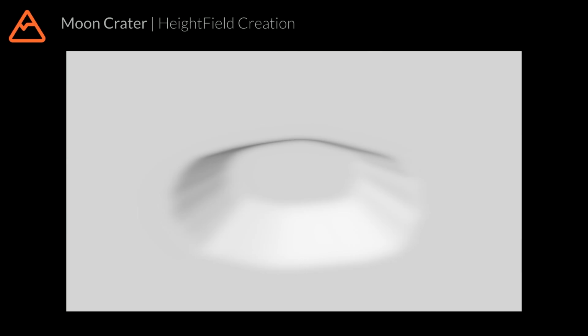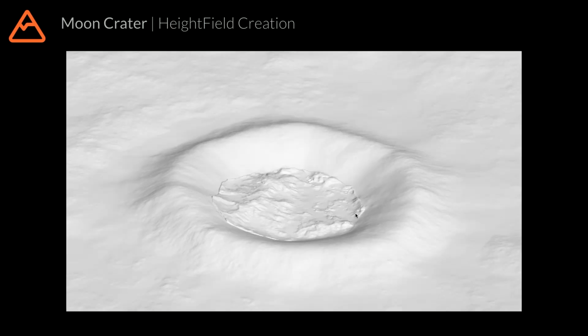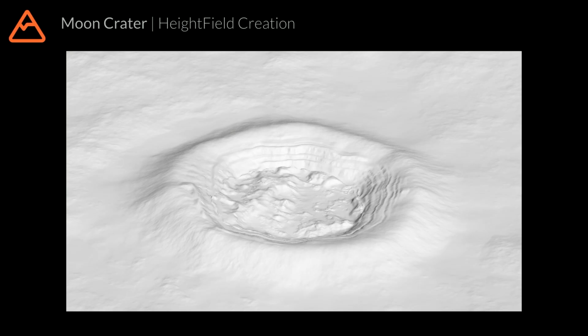And then I'm using the same mask layer to generate a little ramp here, and I subtracted it from my original HeightField just to create this little dent. And the thing is, because everything is connected to just one sphere, I can easily put that sphere in different locations, scale it down or up, and everything will automatically update. And for the insides, I add some terracing we already covered, again a little bit of erosion, some more noises to the sides.